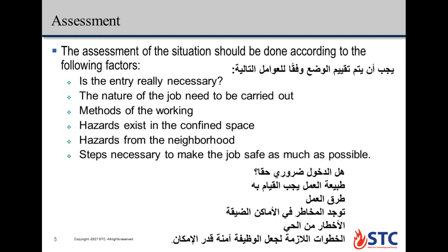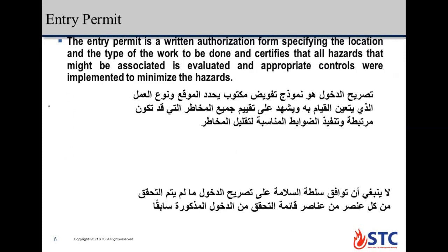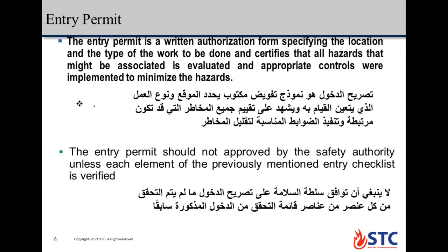The method of the work, and the hazards existing in the confined space, and hazards from the neighborhood, and steps necessary to make the job as safe as possible. Okay.